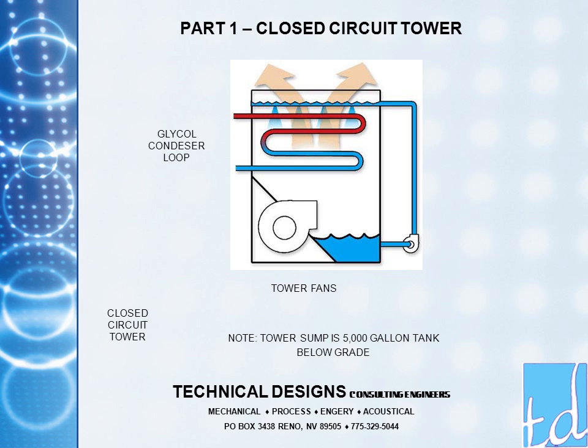The tower has controls to maintain the condenser water loop temperature. During the winter, the condenser loop bypasses the tower altogether, and as more and more cooling occurs in the building, the water is circulated out to the tower coil until the tower basin pump starts to circulate water over the coil and fin. The fans are staged with variable speed drives. Note that at Fernley, the basin of our tower is a large water storage tank underground. This does double duty depending on the time of year.